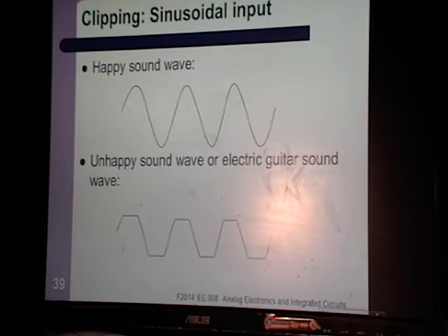All right, so that is amplifiers, the big picture. The summary is you don't always want a giant gain. It depends on what your application is. For us, we're doing an op-amp, so we want a giant gain. Other things are, you can have a voltage in, voltage out amplifier, current in, current out, voltage in, current out, current in, voltage out. Those all have different names.